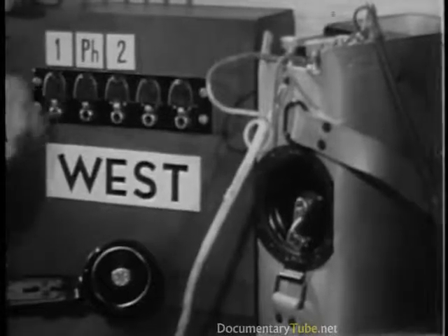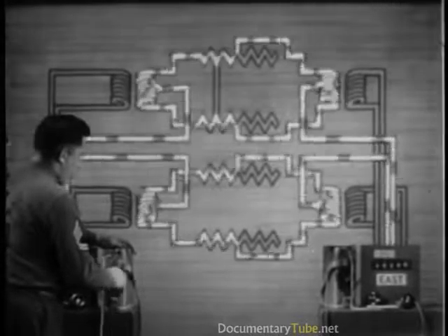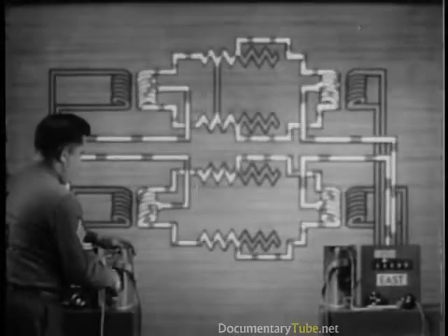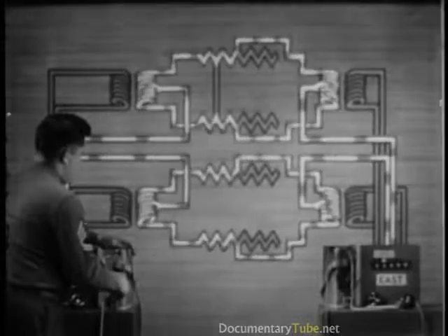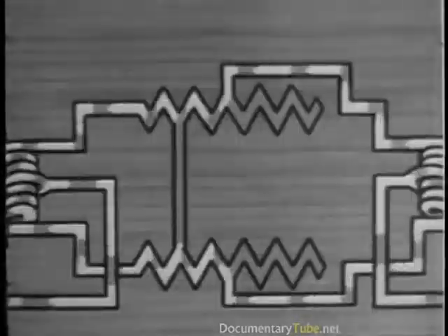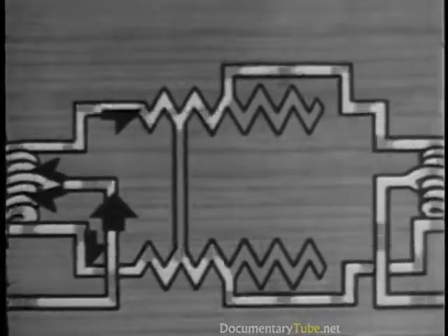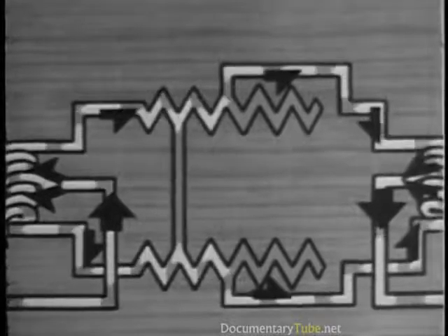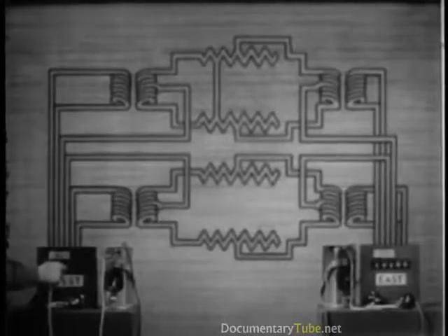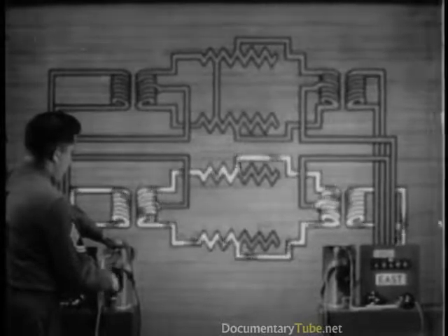When we ring on the phantom, however, we can see that it is unaffected because the 2 halves of the phantom current are traveling in the same direction. When they reach the short, they buck each other, and no current flows through the short. That is exactly what happened in the telegraph channel of the shorted simplex. The other side circuit is unaffected.